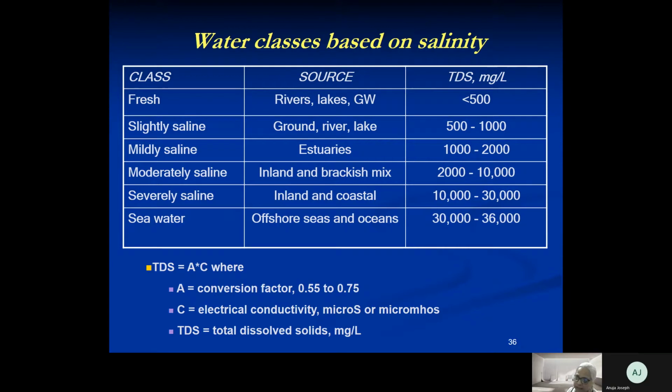Now, total dissolved solids is very difficult to measure in the proper way. It takes more than 24 hours to measure TDS. What we normally do is we take a water sample, you have to evaporate the whole thing and then measure the difference. If you're dealing with drinking water samples, then the change in weight of that sample is going to be so small that it sometimes becomes very difficult to measure in the lab. But that's what is required, that you evaporate the water completely and measure the weight of the salt left behind. So it's a tedious and not easy process.